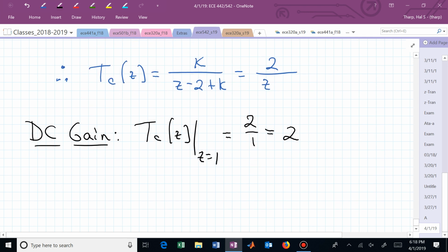Do you see that that was an improvement maybe if we wanted to reduce our steady state error? Now we have a steady state error of 1. We have a faster system. It's now deadbeat in behavior. It gets there in one step and it stays after one step. It doesn't do this exponential of 1/2, 1/2 squared, 1/2 cubed, etc. to get there.